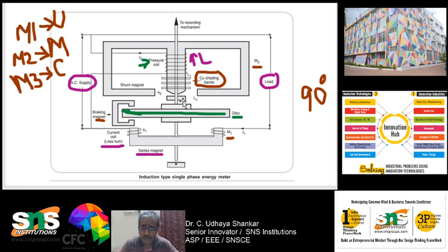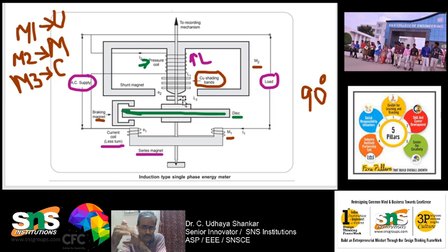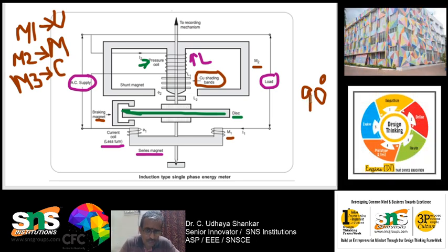So, that display number will be proportional to the number of revolutions made by this particular aluminum disc, and it will be having 10 equal divisions. Hope you would have seen all those things, and inside there will be some reduction gears, because you will be having tens, hundreds, thousands, 10,000 and something like that. So, reduction gears will be there in order to display the quantities correctly without any error. Okay. So, this is how the construction is all about.